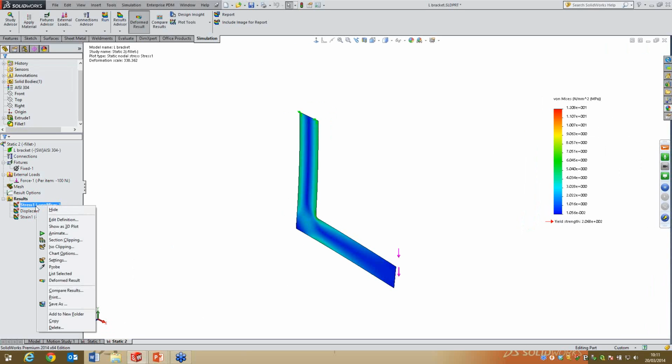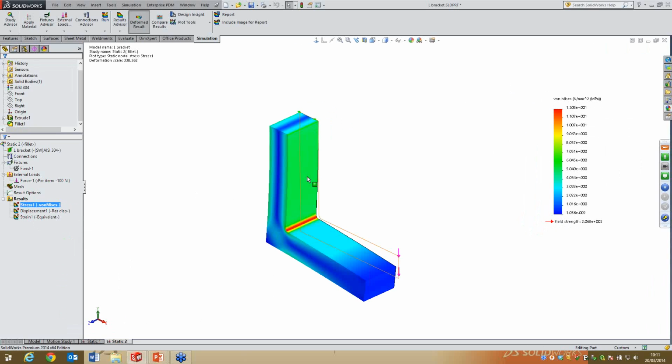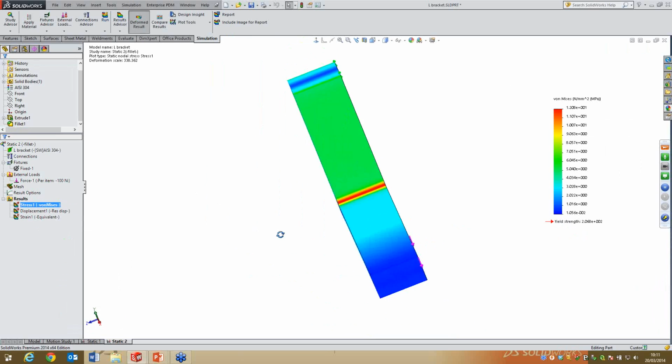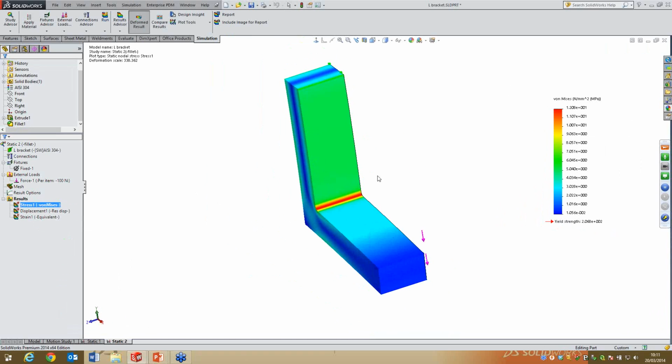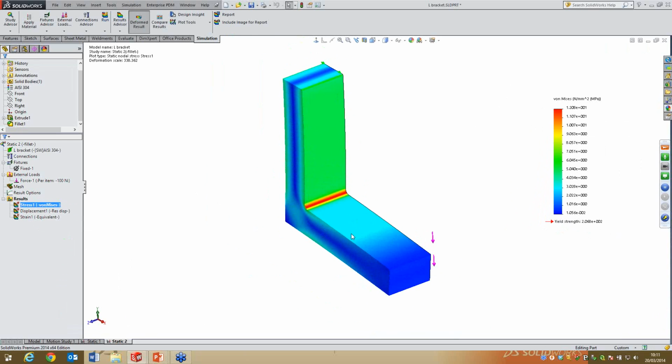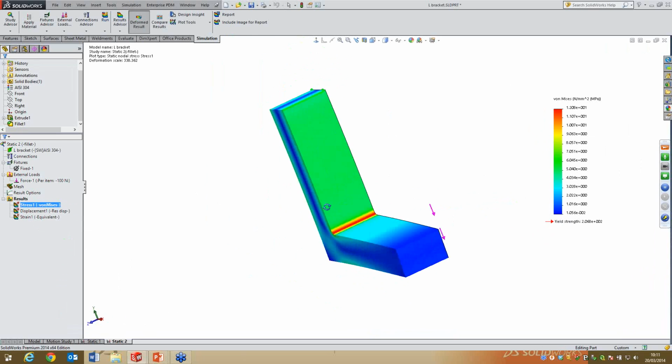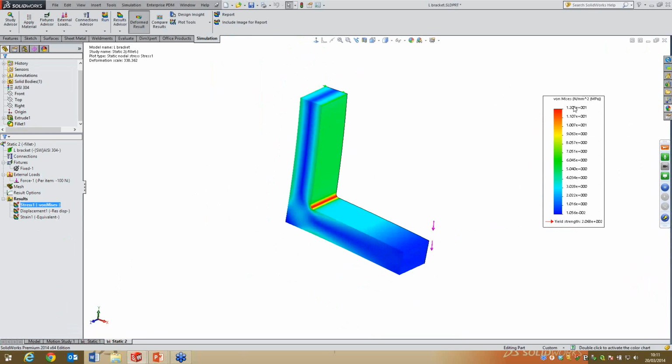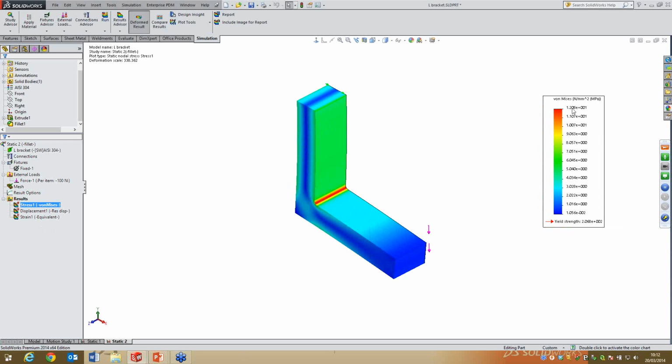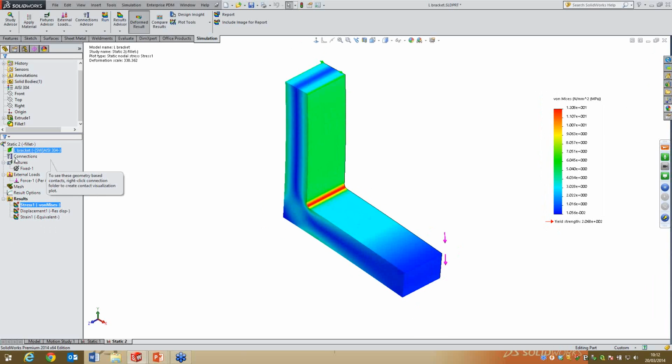So if I show the stress plot here, as I say, it's 12. You can actually show this as a 3D plot, so it's slightly easier. You can see it is all uniform. It is just a render of my section. But let's say that the section depth is important. If I was to put it to 10, this would be in the 30s, so it'd be about 34, 36 MPa. So it is important that you get that right.